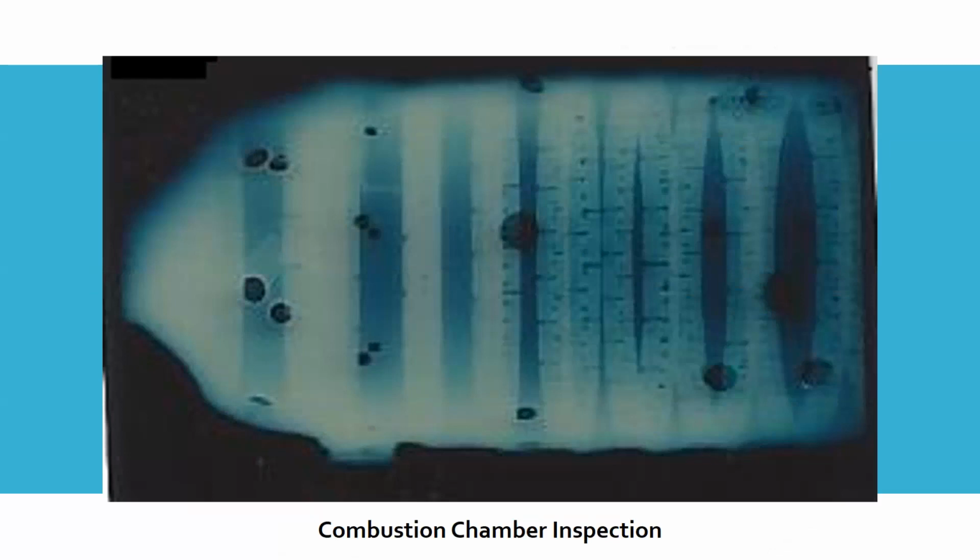You got all the tabs for the cooling air. You can see the lines that divide the tabs, right? What else? What are all these black circles? What's that? There are holes in it, right? They have different holes for air to pass through, right? So you can already identify some of the items here. If you look at it closely, if you were better trained in this, you might be able to see damage or something like that. You could see potentially a crack emanating off of one of these cooling tab slots or something along those lines.